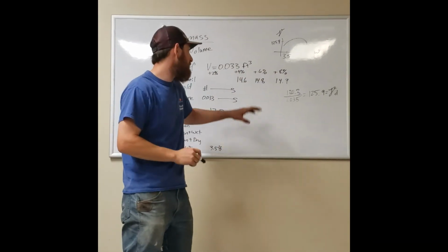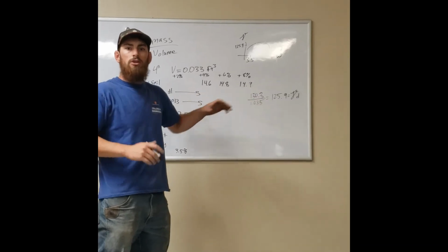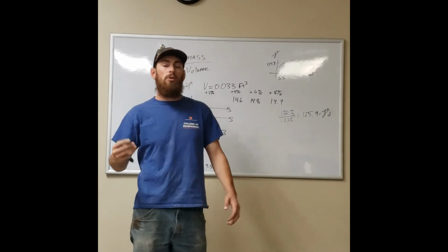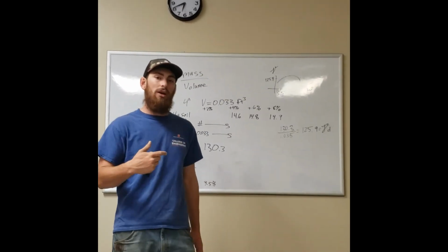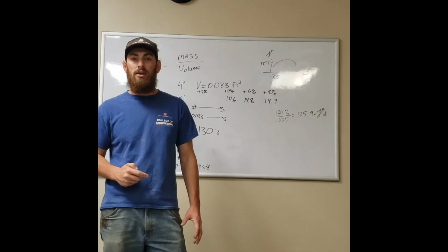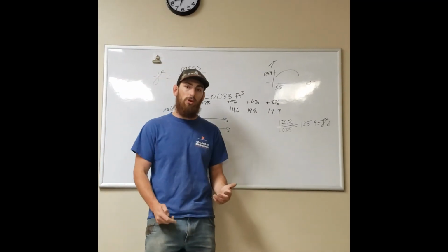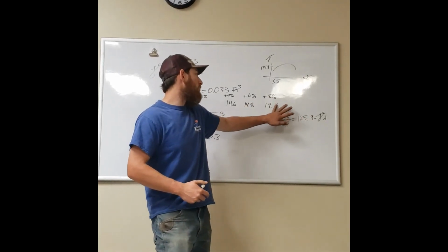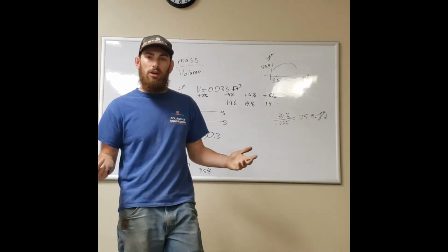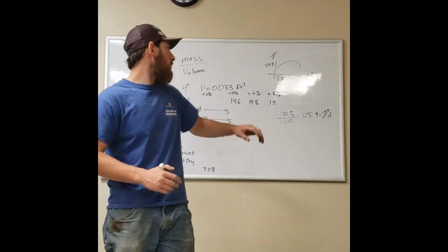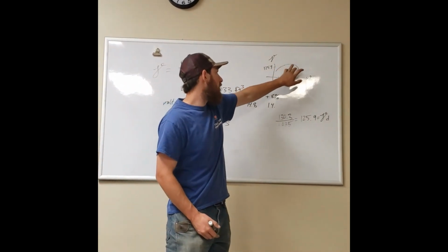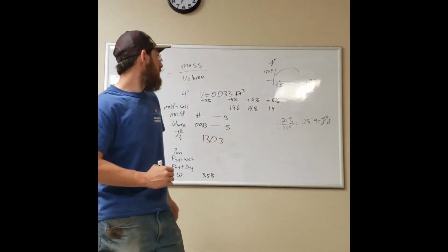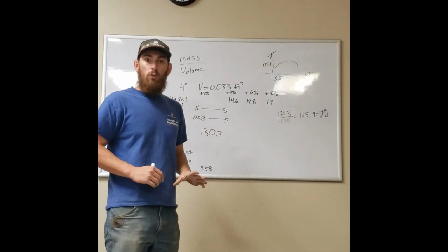Now, when I said that sometimes you don't see it, sometimes it'll keep on going up. Just because it keeps on going up, when you actually divide this out, it will go back down. You just don't see it the first time around doing the procedure, because it is just a different type of soil that's going to leak, which is unfortunate. But I'm going to try and choose one where we will see this drop. It'll go to 14.6 or something. So what I'm going to try and do is get at least 2 points on either side of the curve, so that way I know I have a good curve. That is essentially it for the Proctor.